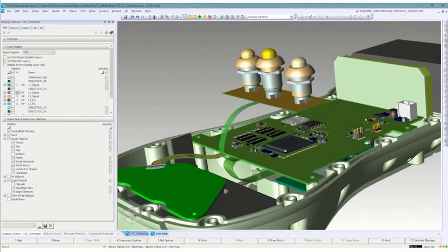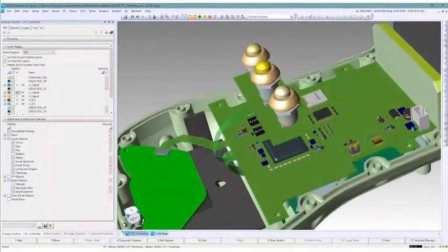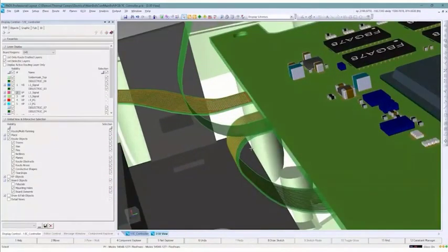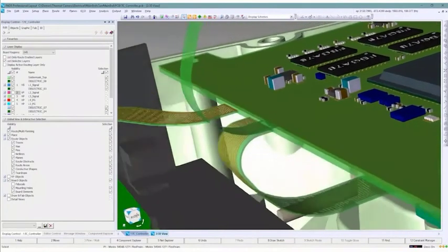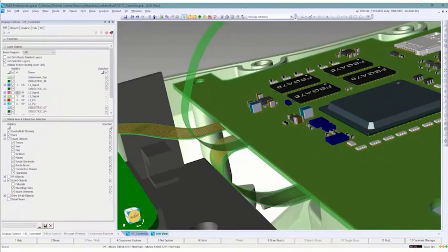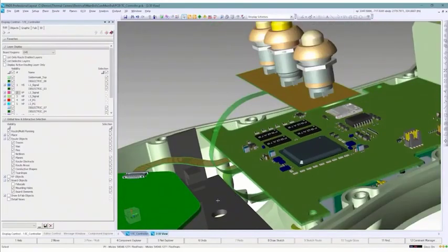And to just do a quick recap, if you've never designed a flex circuit before, not only do you have to learn about the design requirements for flex, but it's also good to know what's required in a tool that'll make your life easier. Being able to do everything in 3D, having tools that have automation for design rules of bend areas, where things can be placed in bend areas, placing components in a flex circuit with it automatically being able to replace the pad stacks for you, knowing that I can only have a certain bend radius depending on the thickness of the flex, and having the tool automatically tell me whether or not I've met that requirement or not is all part of the automation behind using a PCB tool that is flex aware.